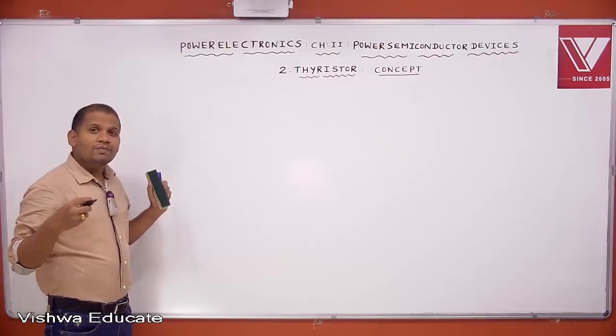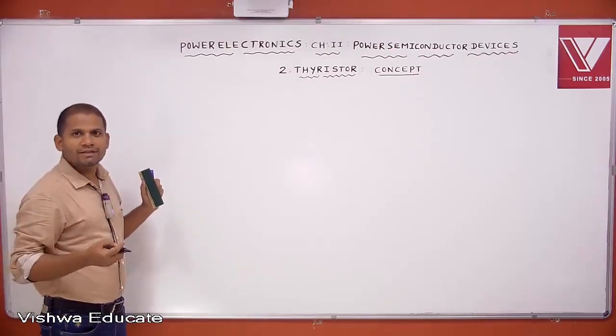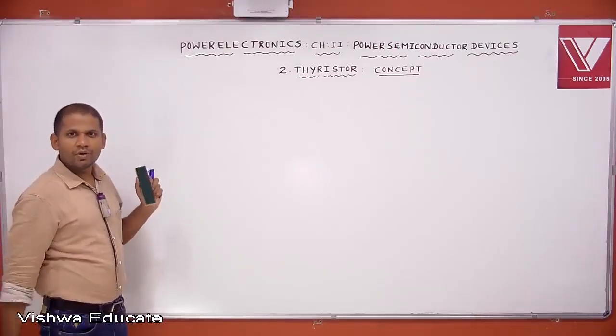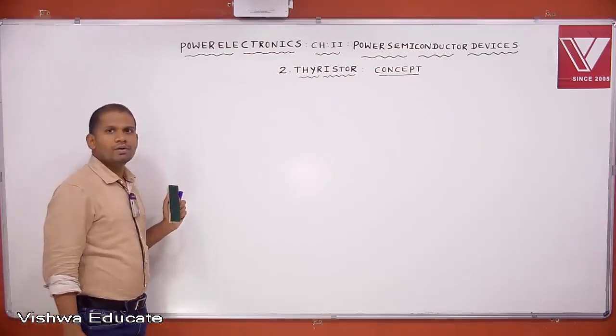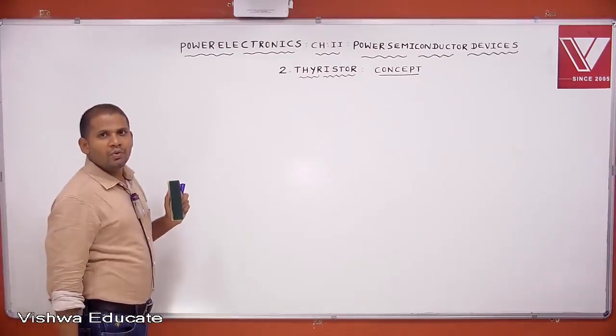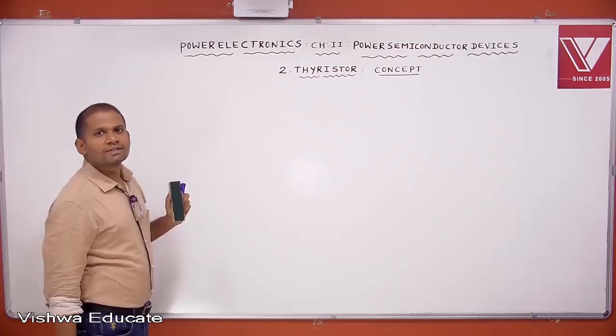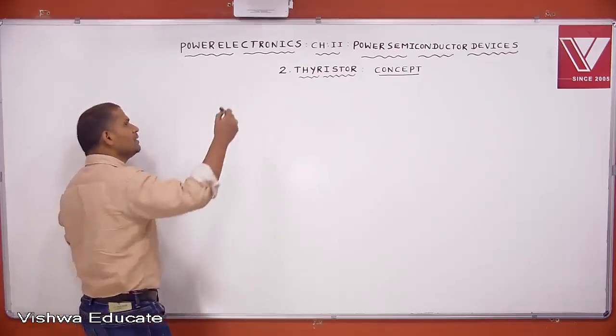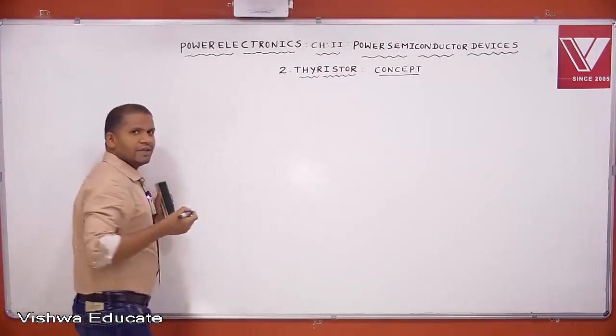That is because of unequal static VI characteristics, there exists an unequal voltage distribution. Due to unequal voltage distribution, the string efficiency is reducing. This is one problem in series connection.